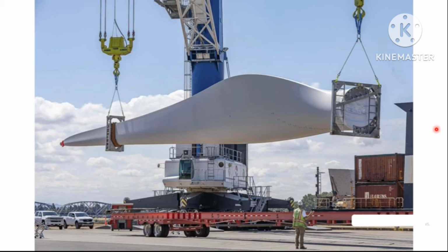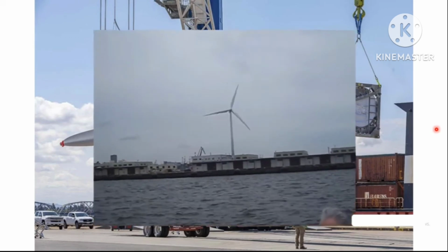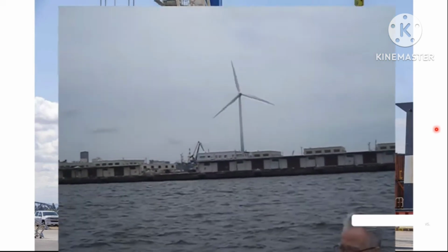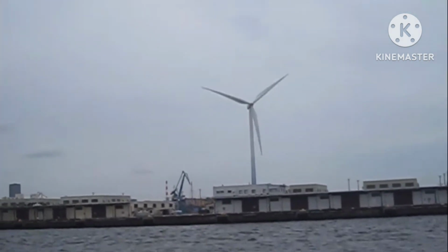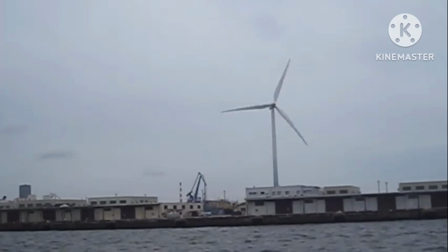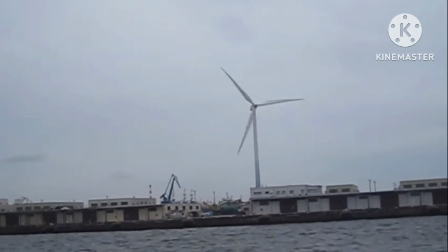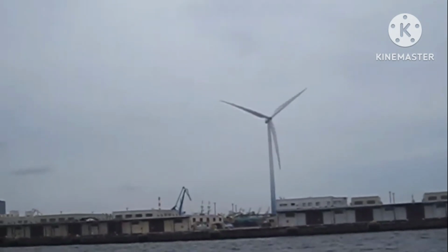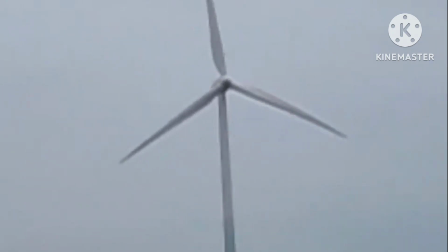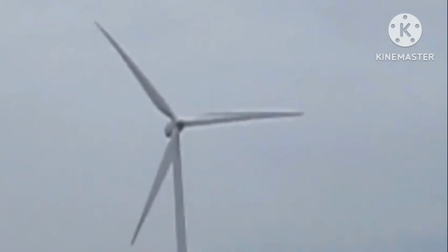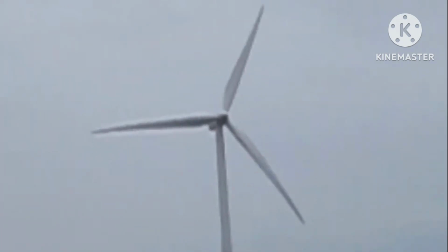With such a huge size of the machine, which needs to stay at a height of approximately 260 meters, it is absolutely necessary that these turbine blades are as light as possible, but they also must be strong against wind power. They should be tough against impact loading such as strong wind and must withstand all kinds of weathers, cold, heat, rain, sea environment, etc. Carbon fiber and glass fiber are used with epoxy polymer to make such huge mechanical items.